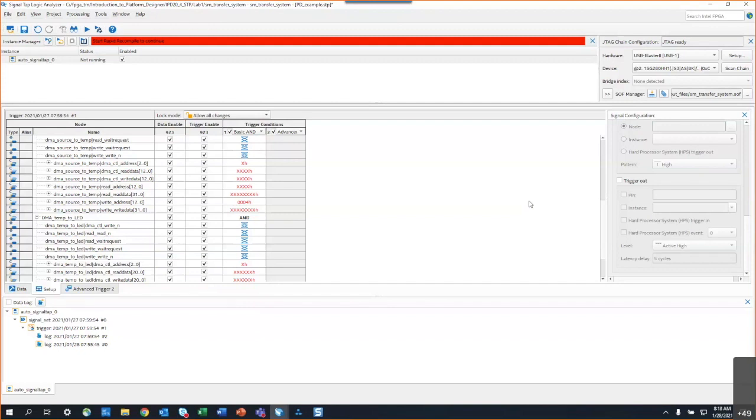Okay, so the next question is, I have noticed that when I'm running a faster SignalTap clock, let's say 250 megahertz, while the ADC is running at 125 megahertz, I would expect the ADC data to be constant during 2 clock cycles of the SignalTap sample clock. But I see that the data keeps changing when the SignalTap clock is running and before a new ADC data is read in, every other clock cycle of the SignalTap clock. What could be causing this, and how can I fix this? So this is obviously the person from earlier.